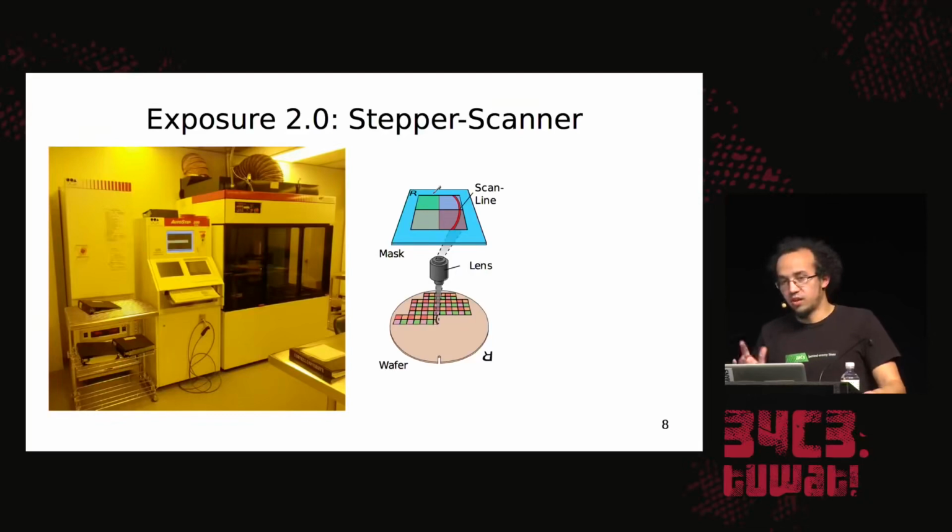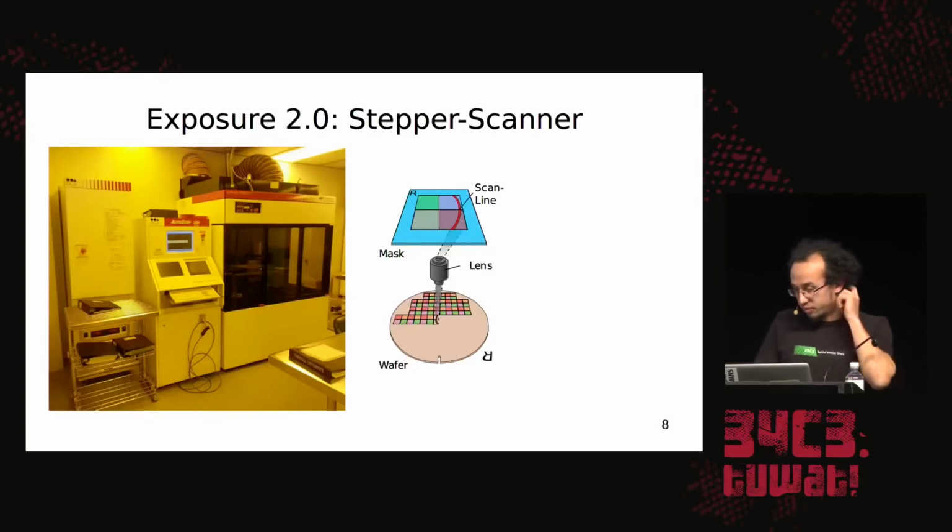And this gives you several upsides. You don't need several copies of your pattern on the mask. And it also allows you to scale down the image here, which sort of takes away some of the necessity to have these really small structures well defined.